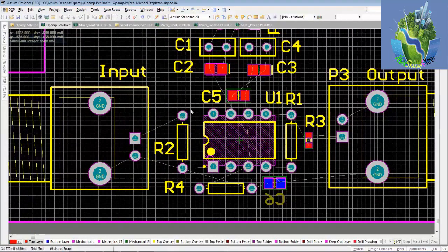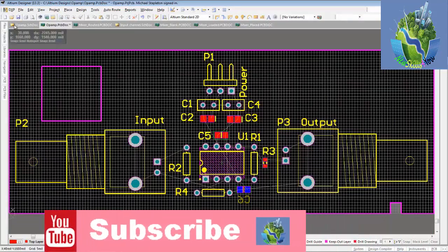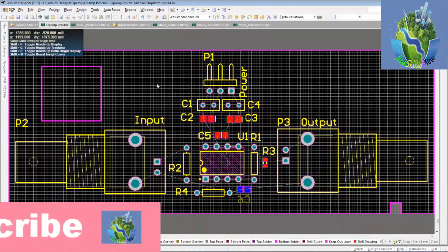So there's a quick introduction to our board shape and our layers. And we're going to see these layers as we keep going. I'm going to add some more layers in our next video, and you'll see about routing, see the copper traces on the top. We'll see about adding planes and adding internal signal layers and removing them. And then we'll also look at changing some of the rules that we have, because Altium has rules, and we'll go and edit the rules, and we can change the width of our traces, the spacing of our traces. So let's do a fit, save all, and we'll finish this video.